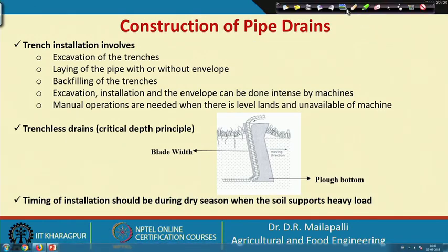The next is trench installation, which involves excavation of the trenches. The first is excavation, opening the soil, and laying of the pipe with or without envelope. Laying of the pipe with envelope if the trench is open, without envelope if it is trenchless. Mostly without envelope is in the case of mole drains.